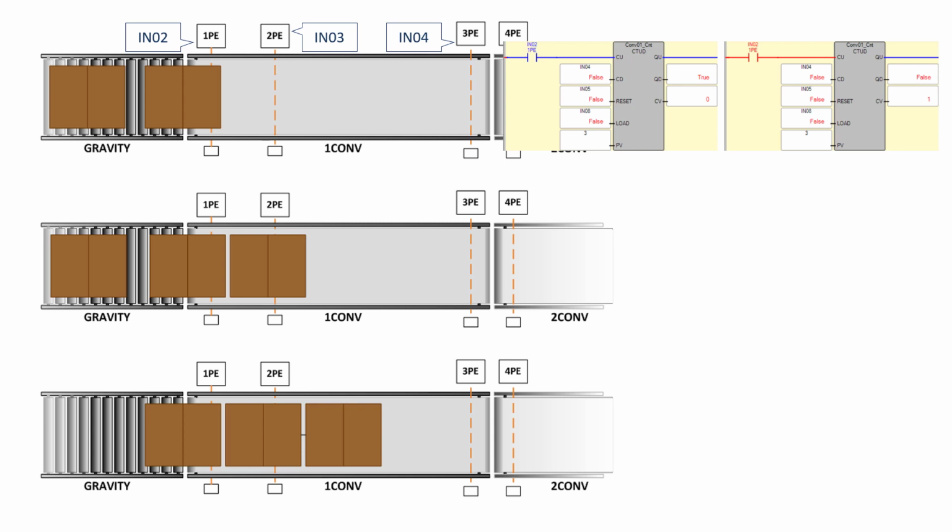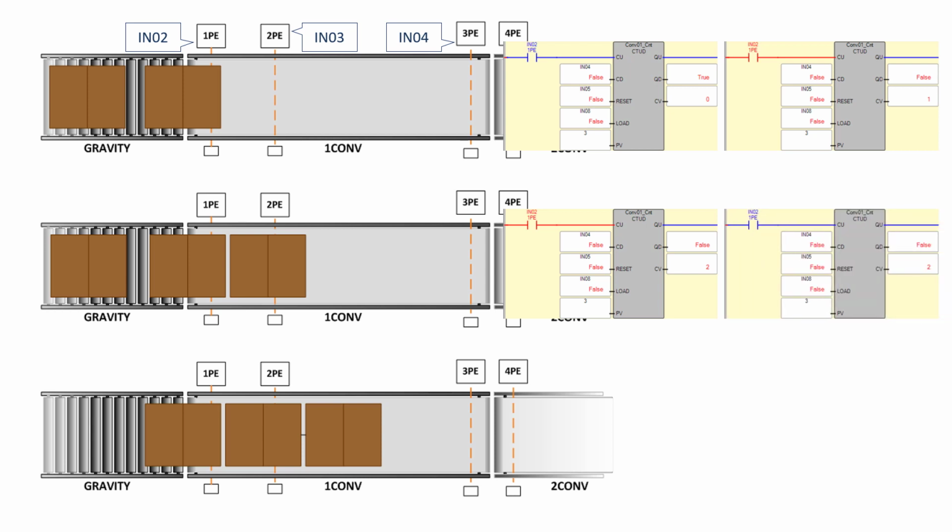When the rung-in condition for the CU control variable goes from false to true, it increments up 1. Then as the carton passes through photo eye 1, you can see in the image to the left that the first carton has left photo eye 1 and a second carton has now broken the beam. It's in the optical path. On that false to true transition, it counts up to 2. Then when the photo eye clears, it remains 2. So there is a little space in between the cartons.